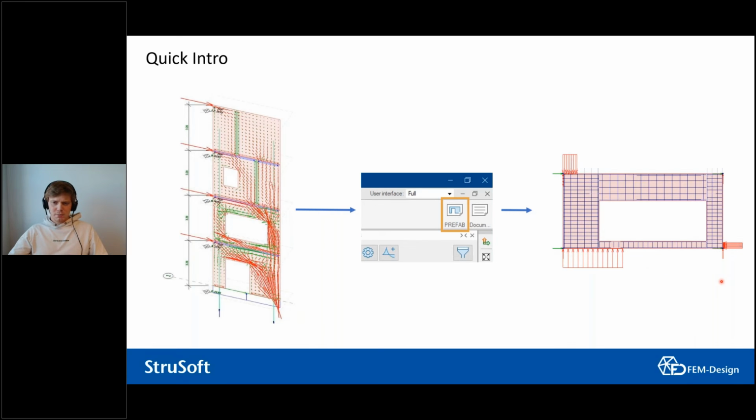You can also get it per element basis. So in this case, let's say you want to calculate these walls afterwards. So you're not just doing the takedown, you're also doing the design. You can export these walls with all the results along the edges.